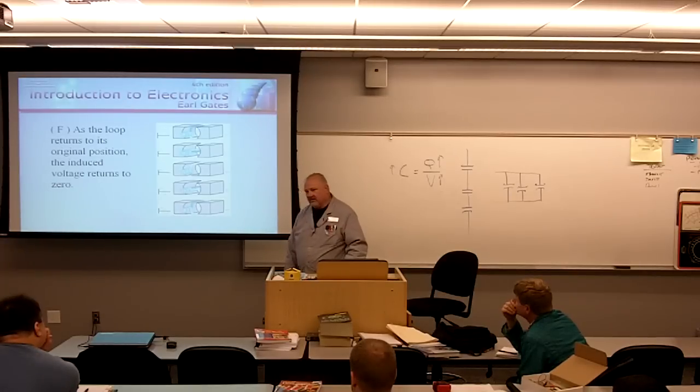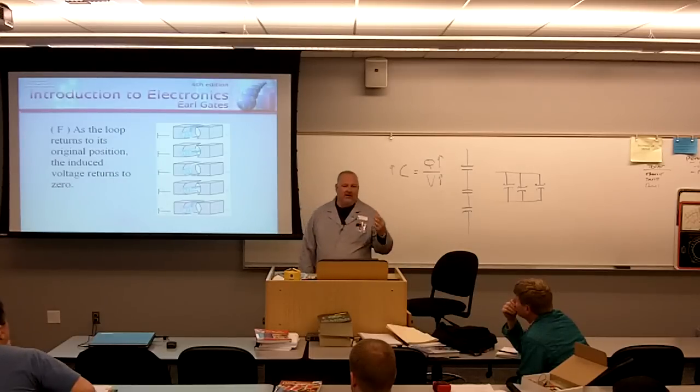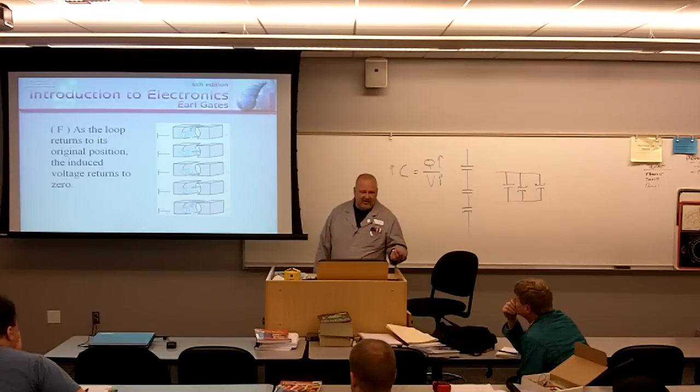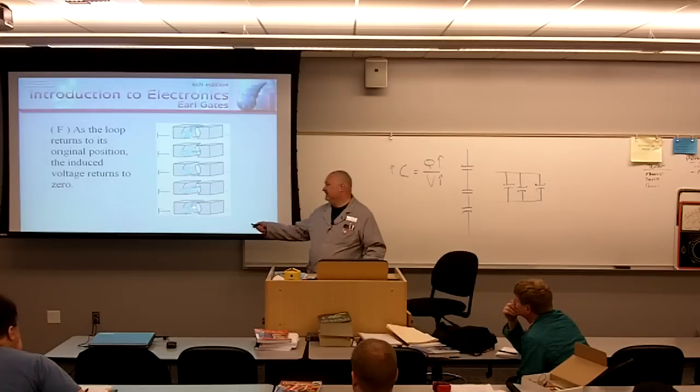So how we rotate the shaft, right? It's really up to us. It could be water from a dam, hydroelectric, it could be a wind turbine that's turning the shaft, it could be a gas turbine, it could be a steam turbine, we could be heating that water with nuclear, with coal, with diesel, however we want to do it. Bottom line is we got to get this shaft turning. Once we get the shaft turning, get the armature turning through the magnetic field, we're generating AC power.